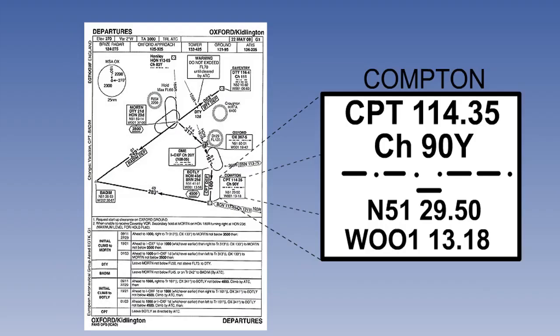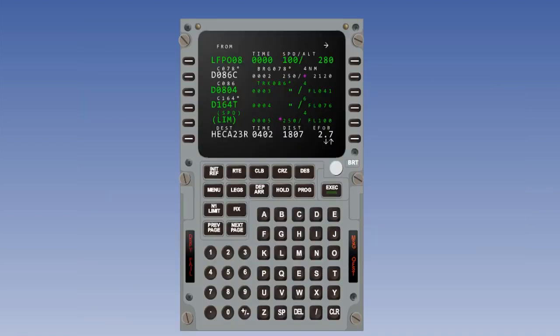A waypoint is a point on the surface of the Earth, designated by a latitude and longitude. Waypoints and VOR beacons are typically co-located to allow for either methods of navigation to be used across land. But of course a waypoint could also be a point over the ocean. The pilot can also manually enter any latitude and longitude to produce a unique waypoint.